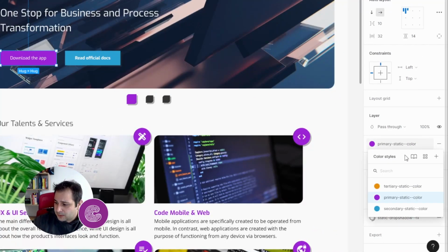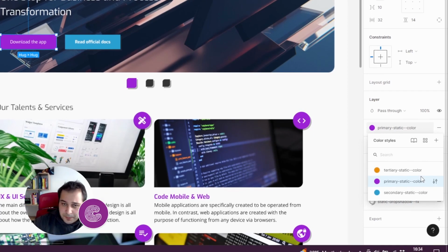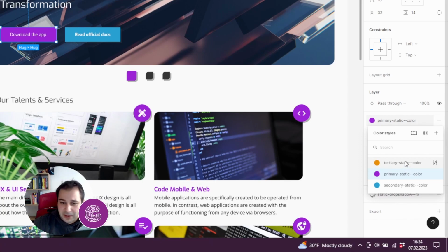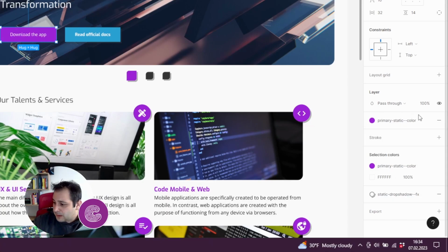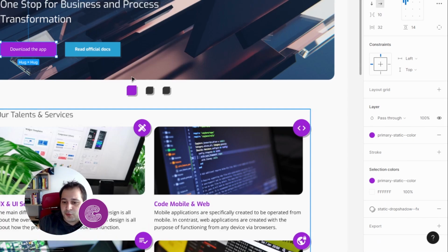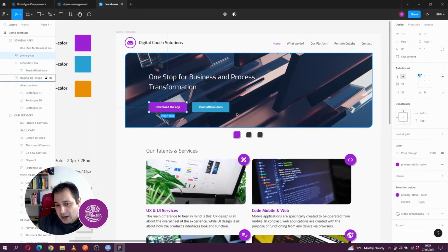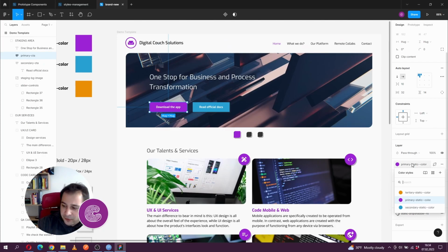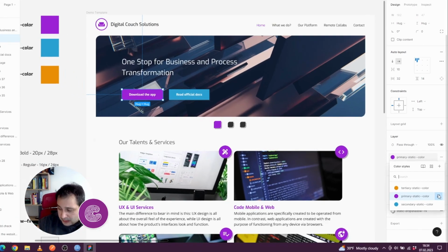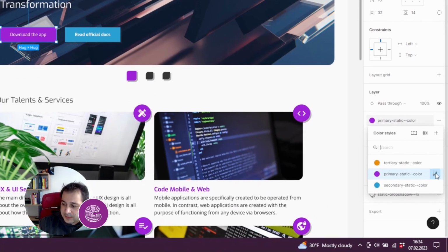Now, if you want to swap styles, basically it means you select the element and you go here in your library, click on the active style you applied, and then change it from the library. Yeah, this would mean that I swap styles. It's not the same thing as editing styles. Editing styles would be when I go into the library and I open that style I'm interested in, from this toggle button.